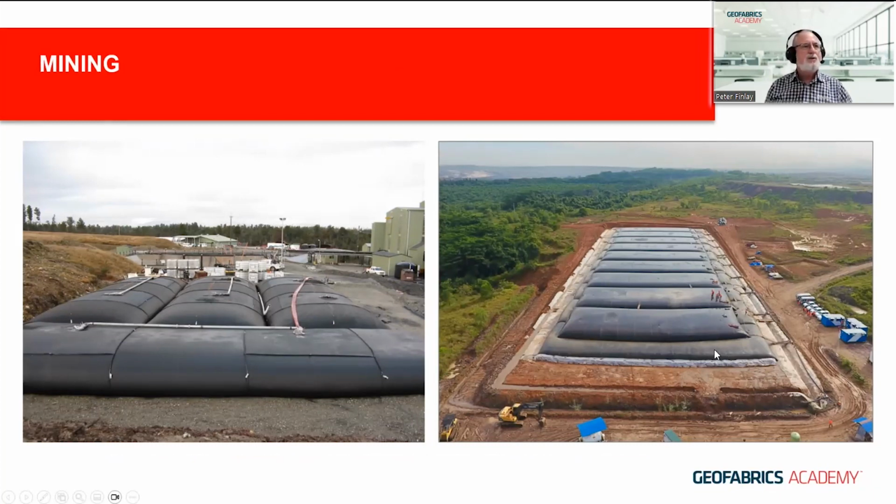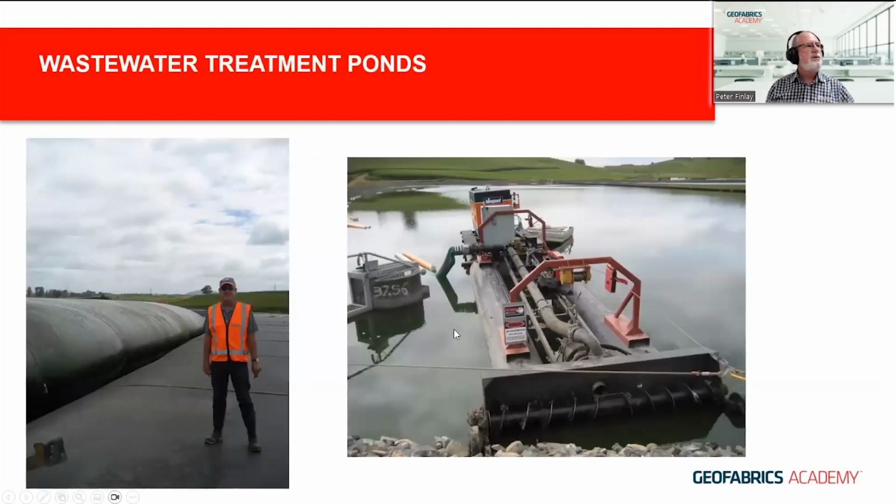There are some special requirements, and it's too much to go into in this presentation, which I'm getting fairly close to time. But there are techniques you're able to employ to stack geotube one on top of the other, and this is generally done with mineral waste more than organic waste, because you need to get this to greater than 50% solids, so you've got some support for the top tubes.